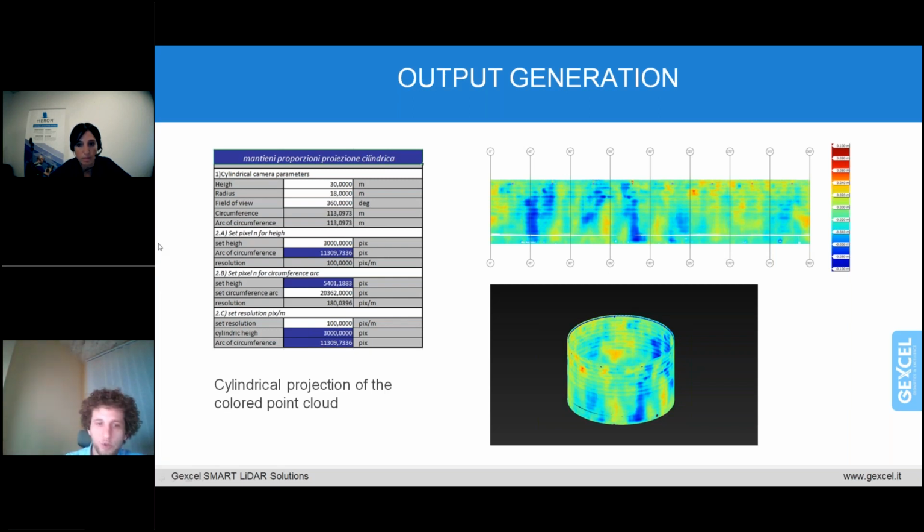What we really love is the color scale, which can be adjusted and tweaked however we like. So if we say that we have to stay within 10 centimeters out and 10 centimeters inside, we switch the color scale accordingly to see how the deviations are distributed along the cylindrical surfaces. Or if the contractor calls us 2 days later that, okay, I understand this, but I have 5 centimeters plus and 5 centimeters minus tolerance.